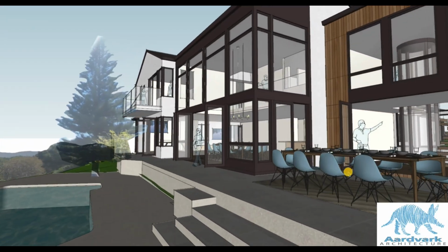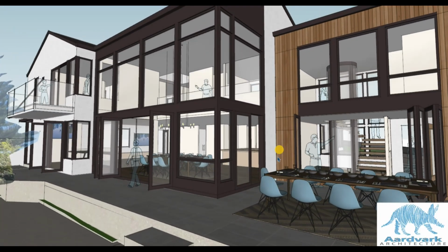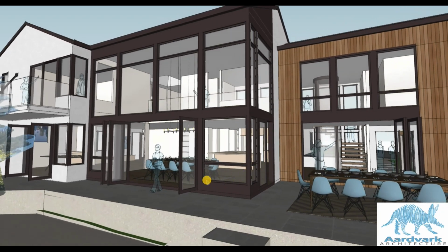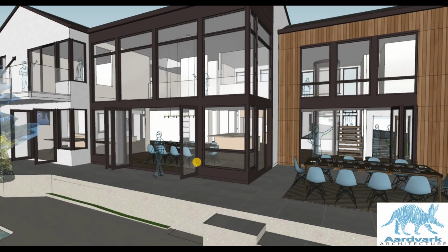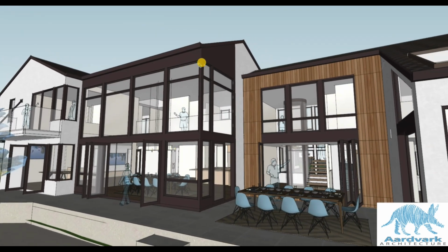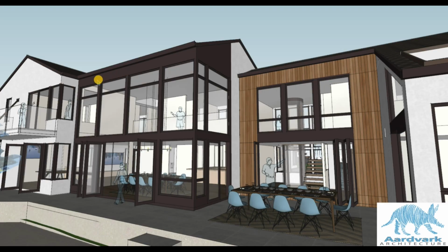All right, so a lot of glass happening here, and a lot of this is operable. These lower sections here would be able to hinge along the top, so you can crank these open to get some airflow coming in across people's legs. And then perhaps motorized would be a pricier option, but we could perhaps motorize some of these sections at the top to also allow for some stacked ventilation. That might be nice.